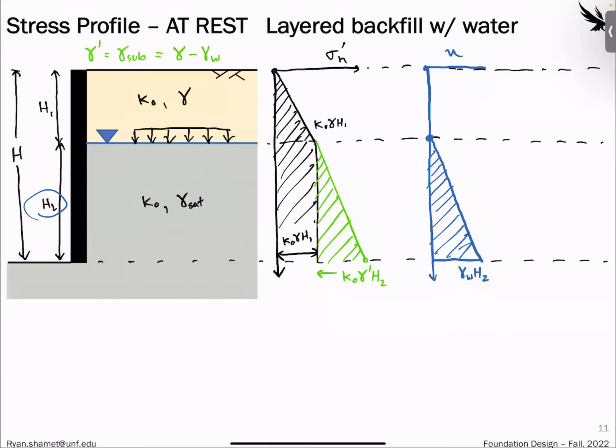Total, right? Yeah. So just to recap, in geotech we design for effective stress, because most of the time when we're talking about vertical effective stress, that is going to be lower than the total stress. The total stress would produce higher strength values, because soil is frictional, so the more we press on it, the more strength there is. That's why most of the time we'll factor out the water, because the water can't be trusted. It can leave, and then we thought it had more strength than it did, but now it's looser.